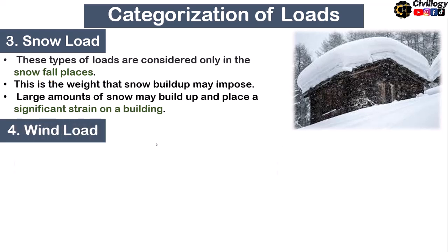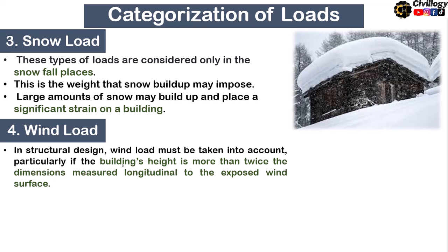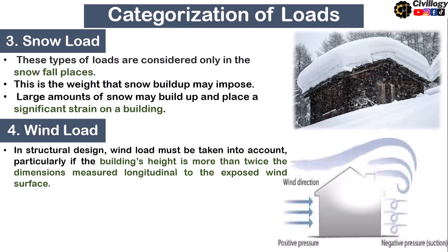The fourth type of load is wind load. In structural design, wind load must be taken into account, particularly if the building's height is more than twice the dimensions measured longitudinal to the exposed wind surface.